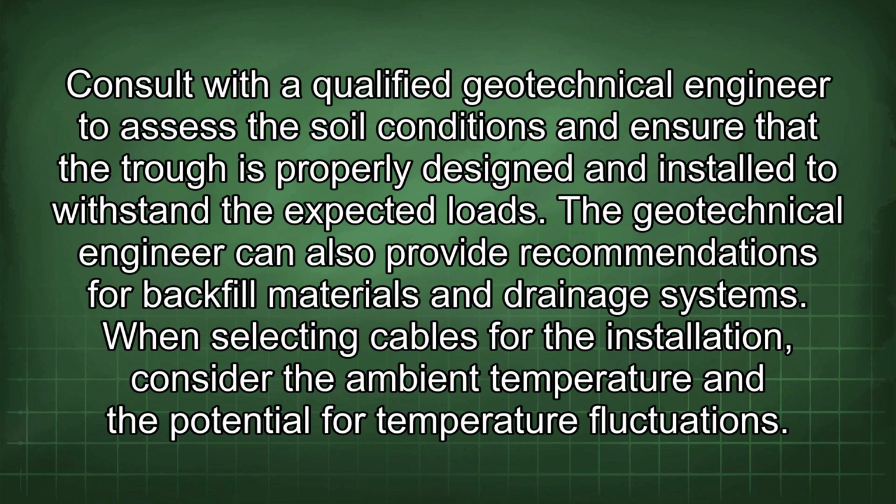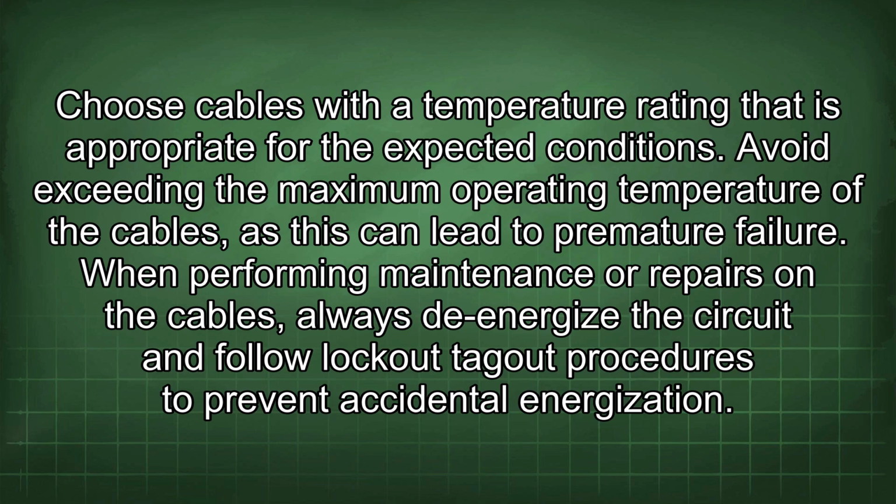When selecting cables for the installation, consider the ambient temperature and the potential for temperature fluctuations. Choose cables with a temperature rating that is appropriate for the expected conditions. Avoid exceeding the maximum operating temperature of the cables, as this can lead to premature failure.